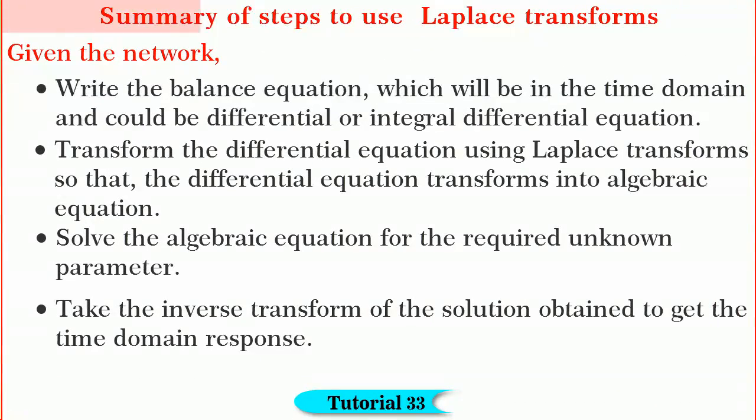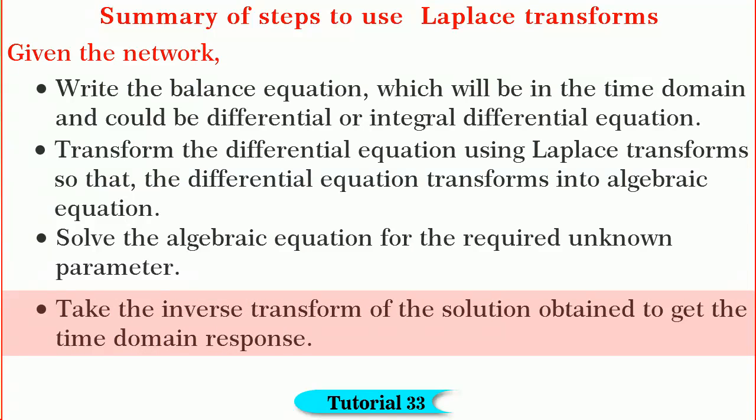Friends, let me summarize the steps to use Laplace transforms. The first and foremost is, given the network, write the balance equation which will be in the time domain and will be an integral differential equation. Then transform the differential equation using Laplace transforms so that the differential equation turns out to be an algebraic equation. Next, solve the algebraic equation for the required parameter, and finally take the inverse Laplace transform of the solution to get the time response if required.